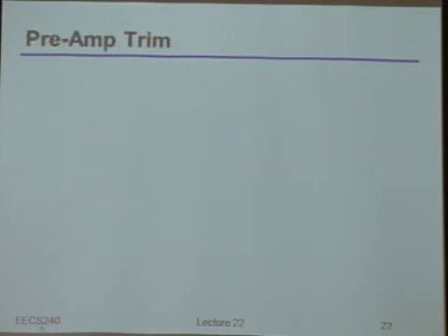And by the way, to do that, let me show you what I think is typically the easiest or best way to do this, and we'll get to exactly the point that you're making. If you remember, we argued a while back that you were probably going to have to use a preamp in your comparator simply due to kickback, simply from an isolation standpoint. Well, I would actually argue that once you've got that preamp, your best bet is most likely to do the offset cancellation inside of the preamp. There are several different reasons for that. But let me draw how that might look, and then I can explain why I say that.